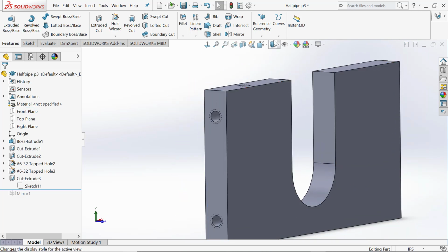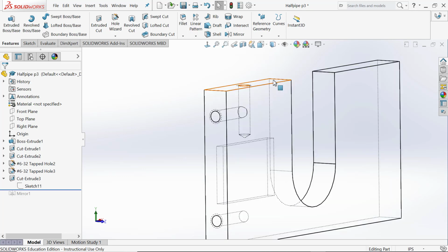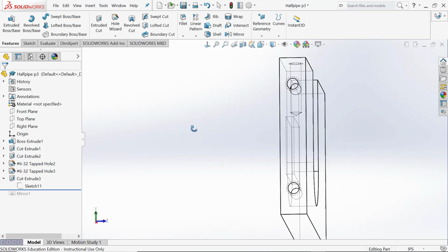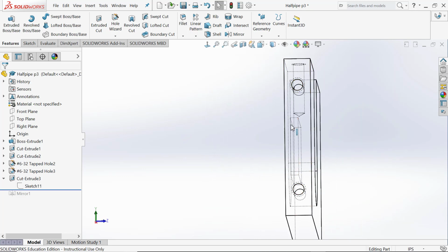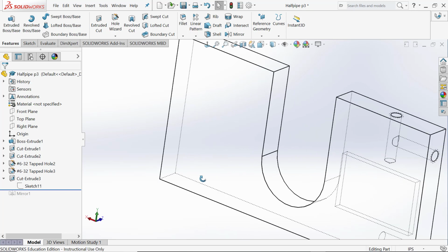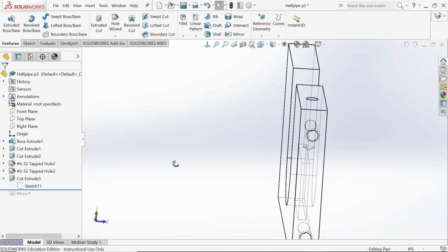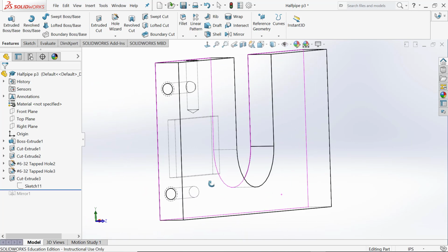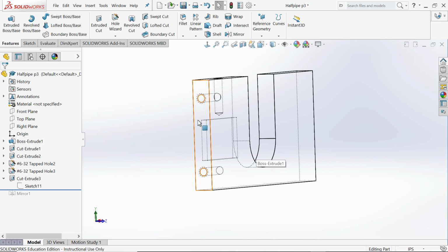But let me show you something interesting. If we change it to the transparent, there actually is a cavity in there, starting in the front plane and offsetting from the surface by 0.05. So the deal is it cut extruded from that plane where the sketch was drawn, offset from the back surface, but that's not really what we wanted. Now, there are a couple of ways to approach this. The way I would prefer, Rohit, please pay attention.